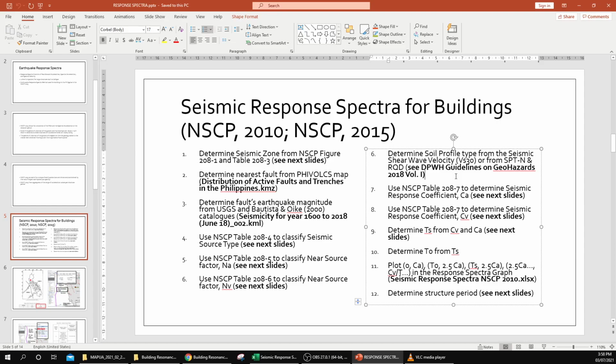They are typically categorized as special problematic soils in a seismic design. So your liquefiable soils, your collapsible soils, your soils that are prone to consolidation, they are your special consideration soils, and they actually need a specialized analysis. But I don't commonly see it here in the Philippines for some reason, although it's specified clearly in the NSCP. So anyway,